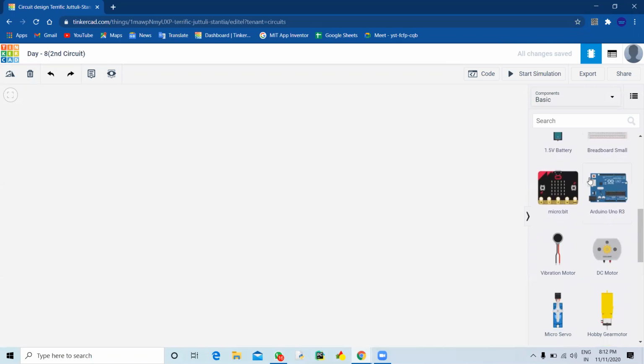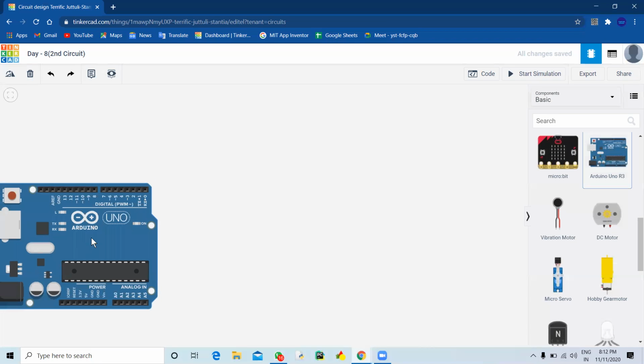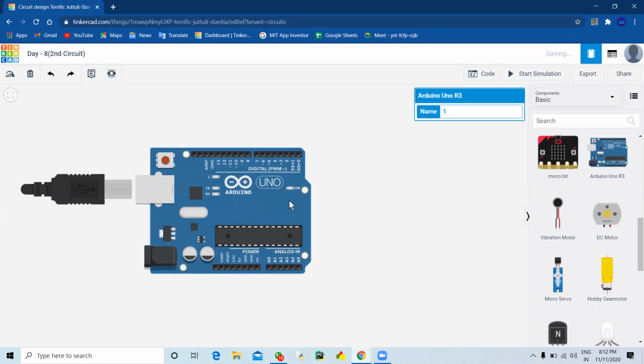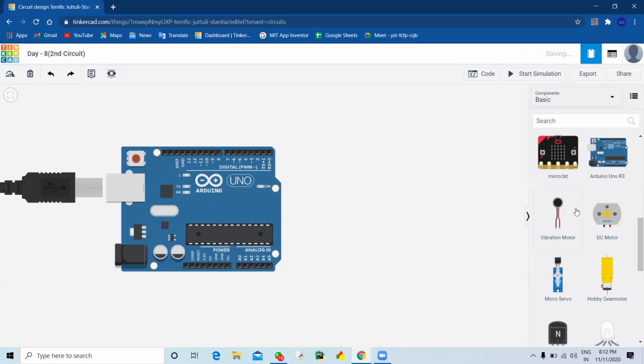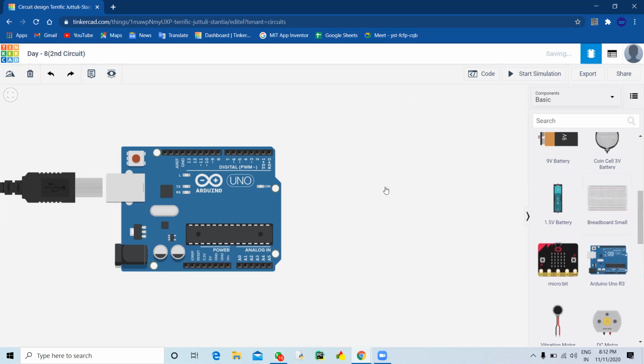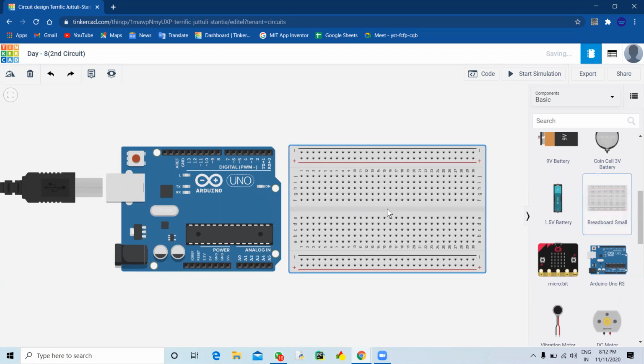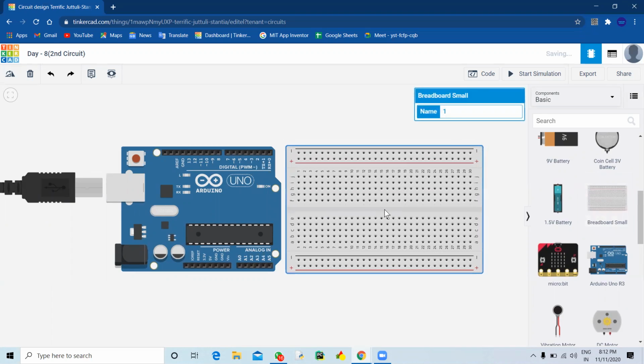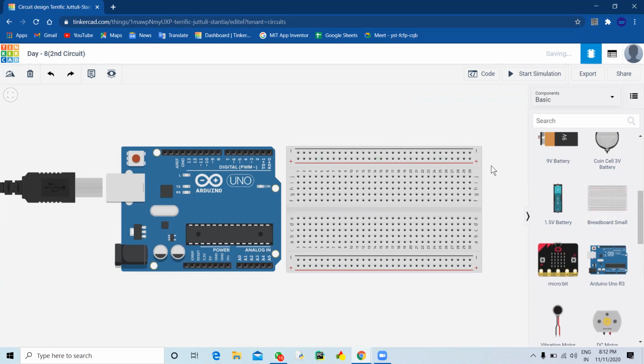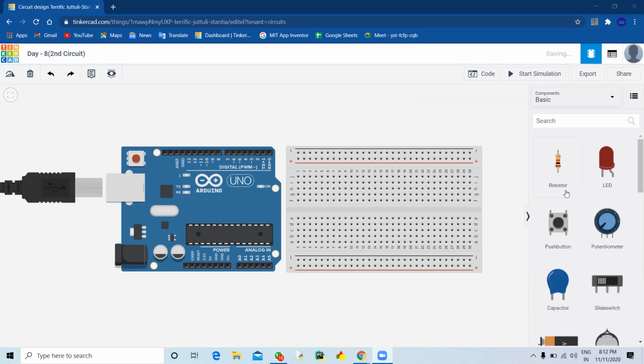So this would detect obstacles that come in between, let's say a car. If we connect this device to a car and there is some motion, anything in front of the car, and the distance is less than 100 centimeters and the motion is there, then what should happen? A buzzer should ring and the RGB LED should turn green.